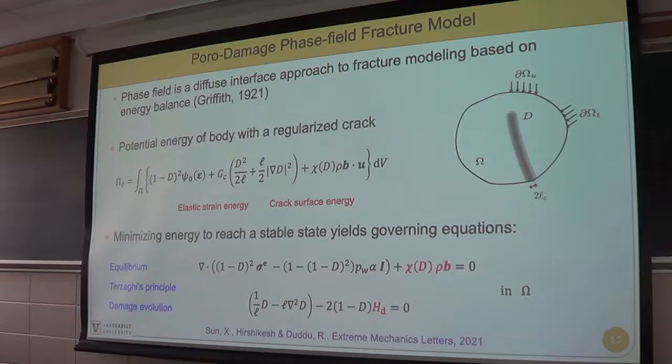We do some more work to introduce the fact that there's also water pressure in the fracture, so we incorporate Terzaghi's principle from soil mechanics to incorporate fluid pressure within fractures. I won't go through all the math details on that. And then we have the body force term, so that's equilibrium. That gives us the stress state, and that stress state defines something called a crack driving force that tells us how the fracture will propagate.